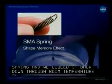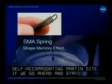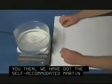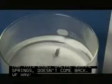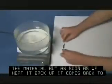So if we could go ahead and start the movie then. We've got the self-accommodated martensite. We go ahead, we pull on the spring. In this case, unlike normal springs, it doesn't come back. We've de-twinned the structure in the material, but as soon as we heat it back up, it comes back to the original high temperature shape, which is the spring shape.